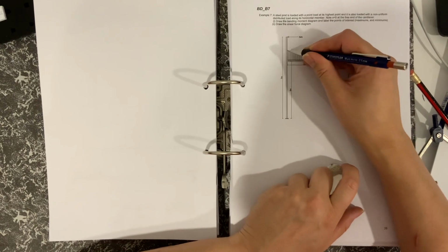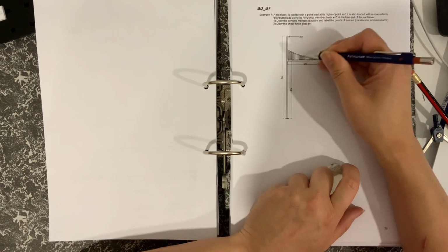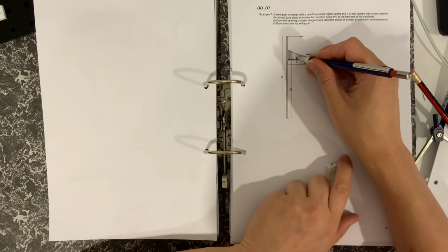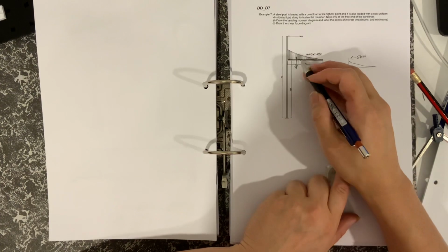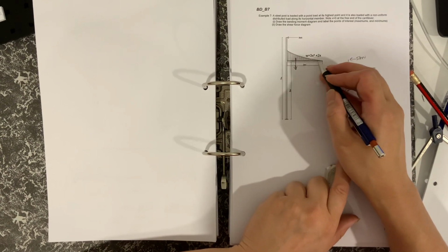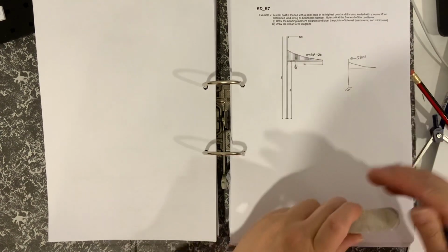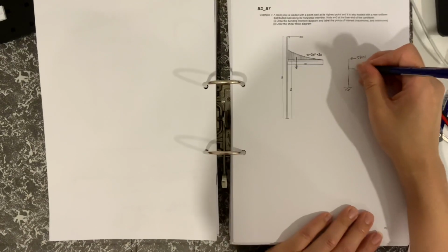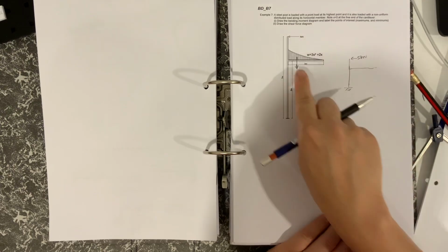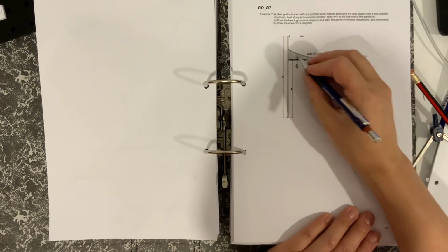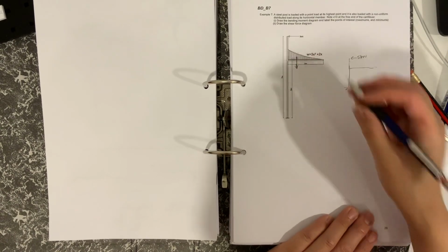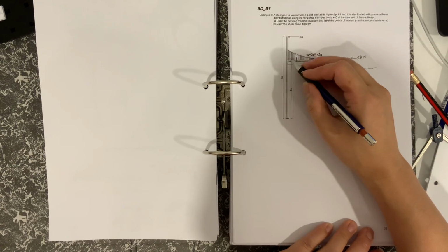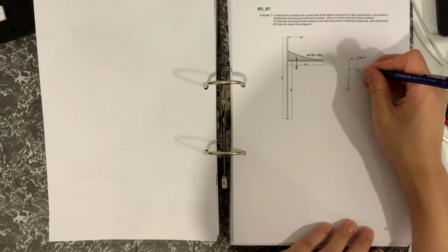You could look at that shape and work out where the center of gravity of that shape is, and that would be where you could say the equivalent force is applied. So you could split that problem, and instead of having the UDL, work out the centroid of the UDL and apply the force, which would be the area under that curve, to here.